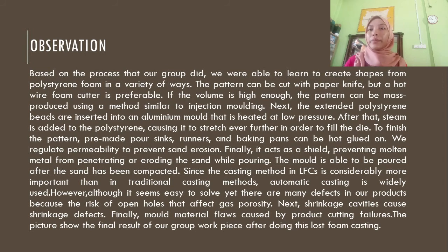We regulate permeability to prevent sand erosion. Finally, the coating acts as a shield, preventing molten metal from penetrating or eroding the sand while pouring. The mold is able to be poured after the sand has been compacted.